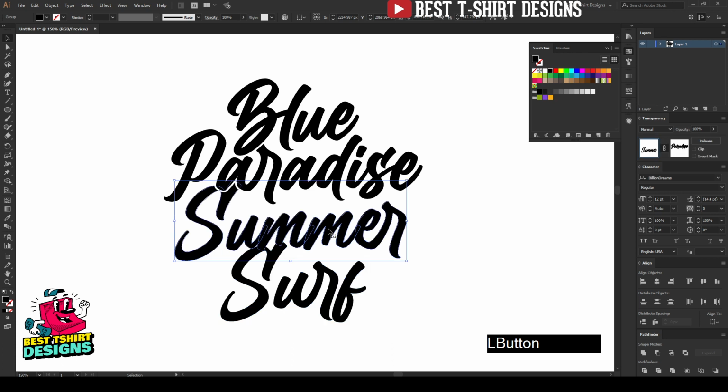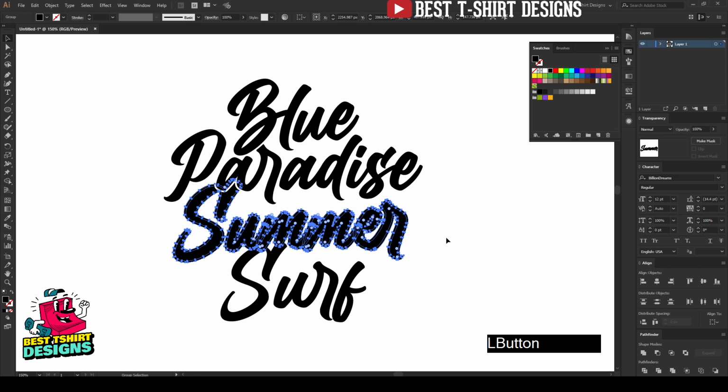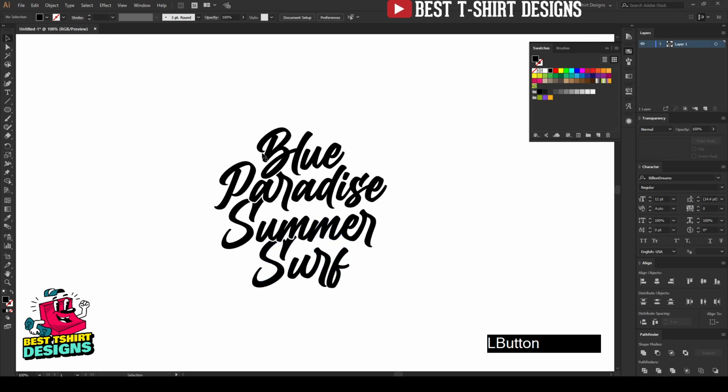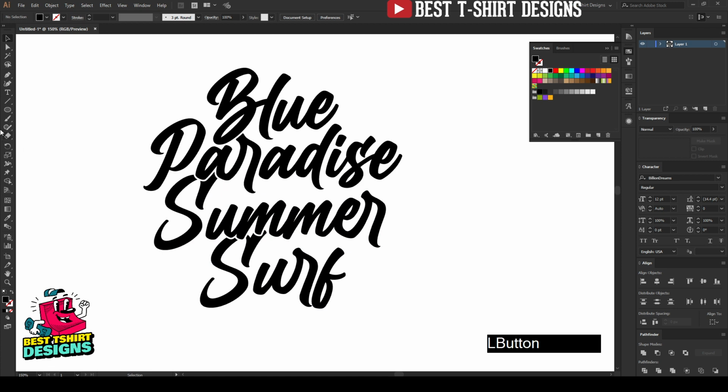I'm going to select this summer text again, create an offset path, same size, Ctrl X to cut. If I move that up like this, I can open the transparency again, press Ctrl F. So Ctrl F will make it look like this. So my text part is done here. Let's group everything so that I don't lose its position.